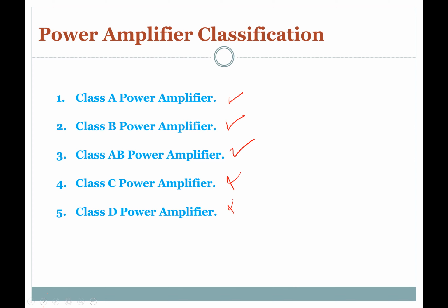So quickly, let's look at what we have here. Just to give you some more insight, on the basis of the configuration and the mode of operation, amplifiers are normally classified, as I have already stated, into different classes. Classes of power amplifiers include, as you know, A, B, C, AB, D, E, and so on. This classification is one of the most important for power amplifiers since it reflects the trade-off between efficiency and linearity.